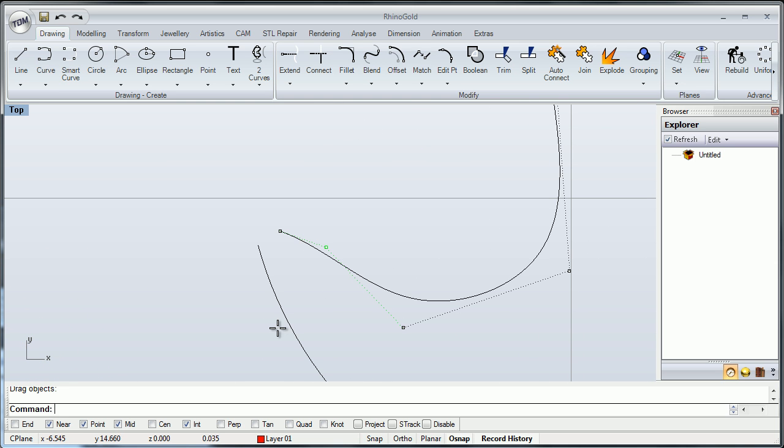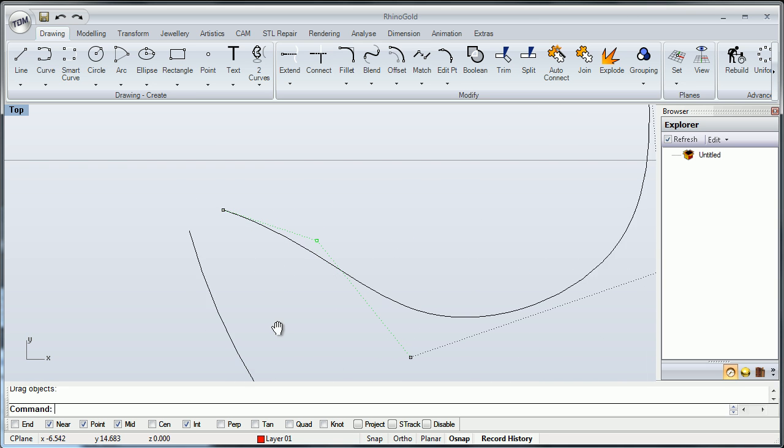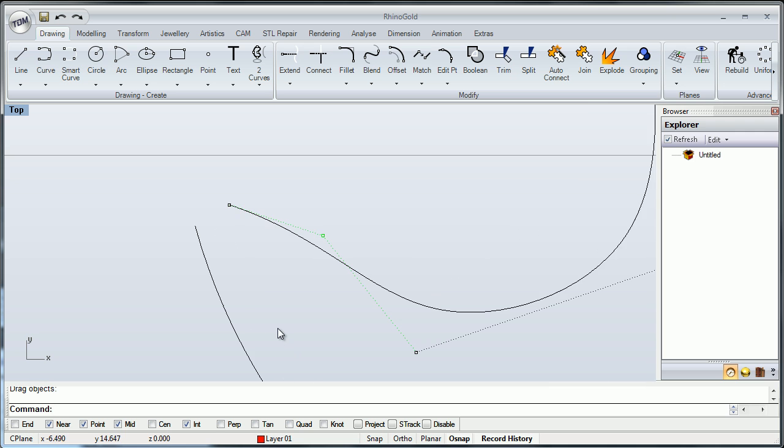For example, I don't like to match that. I will define here. Let me talk about another trick. I'm moving this point, and I have activated here the OSnap, and obviously I have Near. It's deforming too much, but I want to define in the middle, and I don't have the option. Obviously we can come here and disable it, but to save time, when you have this problem, just press the Alt key and automatically disable the OSnap. You see, now I don't have any problem.